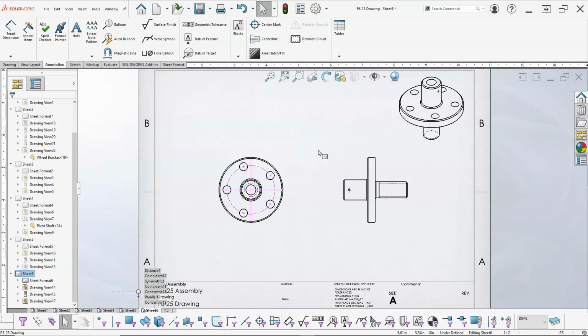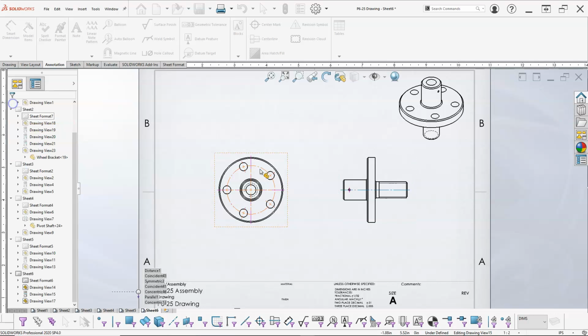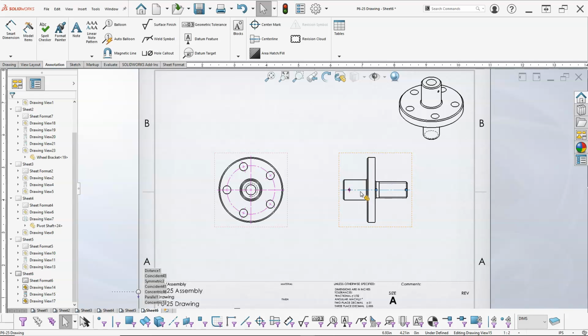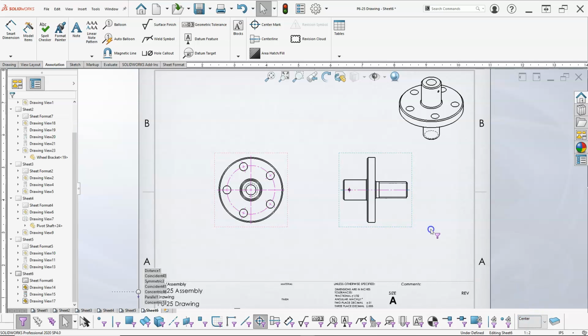Alright, and then I don't know if I need a center line. Let's go ahead and put a center line in. Now in the options, when they apply center lines, it gives the option for applying a layer to the center marks, but somehow I've never quite gotten it to do it. Oh, don't need that as a filter. I just need to change the layer to center. Okay, so F6.